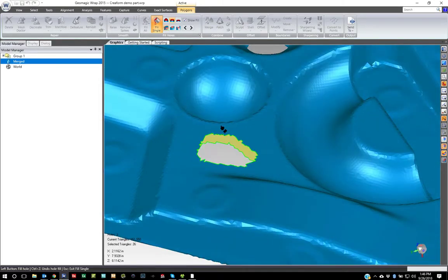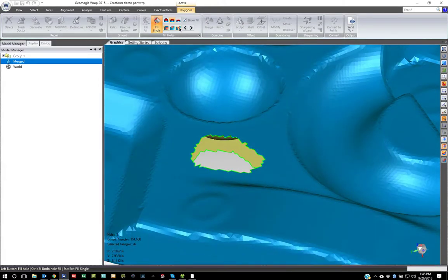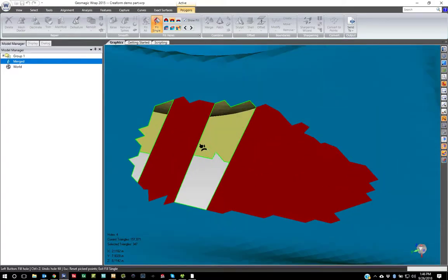Now, if I want to fill a partial or bridge, these are the different methods. So I've been doing fill complete so far, where I just click on the entire boundary and it fills. But you do have the ability to do a fill partial, which I can click a point, another point, and select which half I want to fill. And then you also have bridge. Bridge likes you to click and drag, and it will make a bridge across. So you can see here, there.